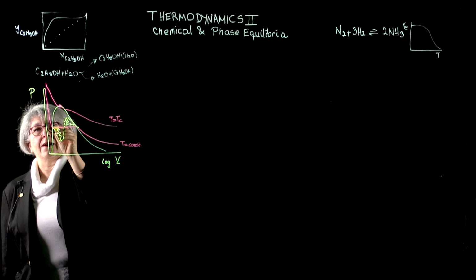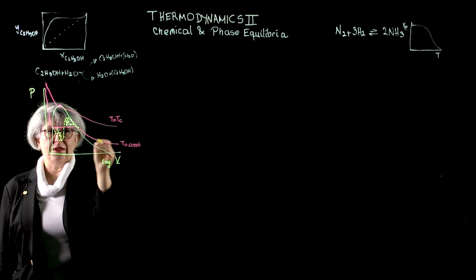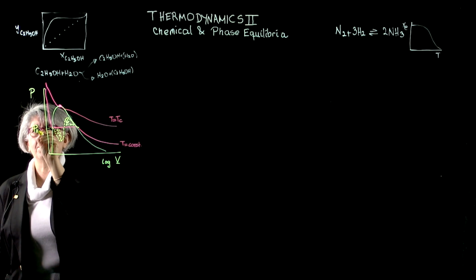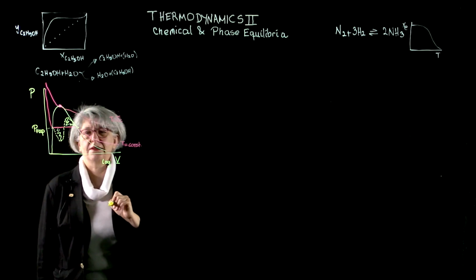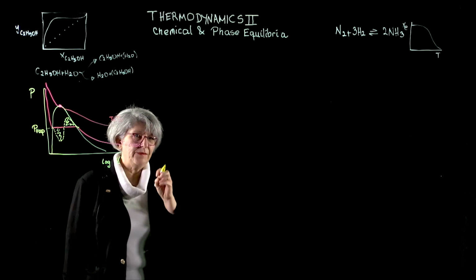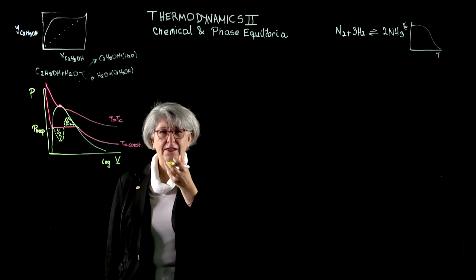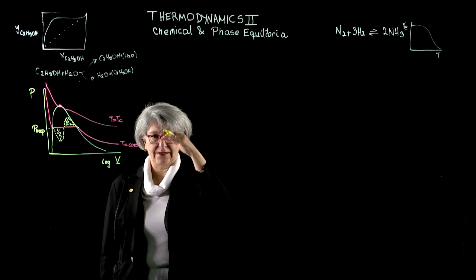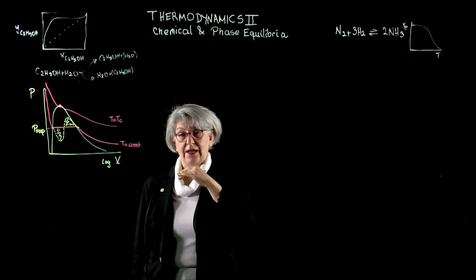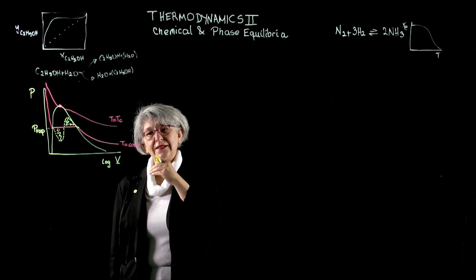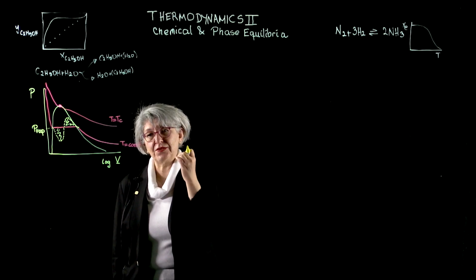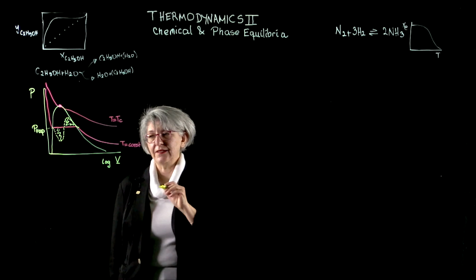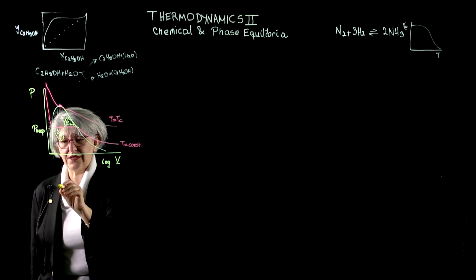Now here, at this temperature, this curve says that the vapor pressure of this fluid is this. This is measured experimentally. We keep the liquid at a constant temperature. We have a system that measures a pressure until the liquid phase has sufficient vapor to saturate its vapor.